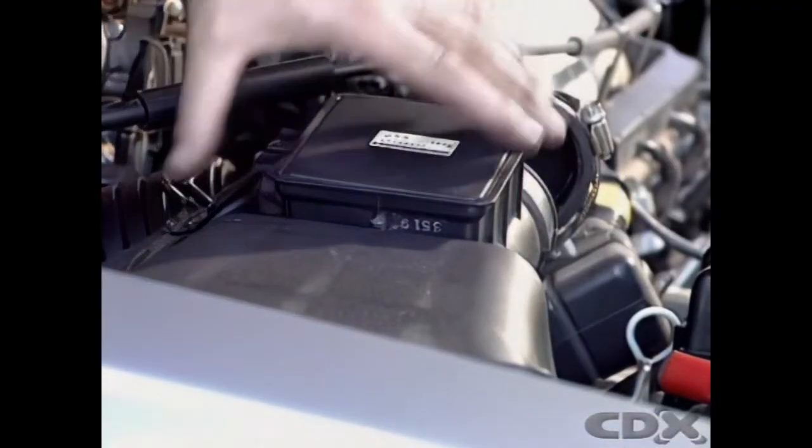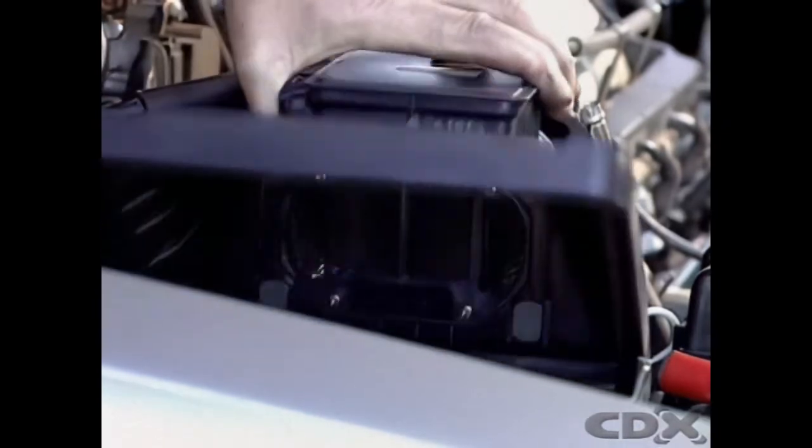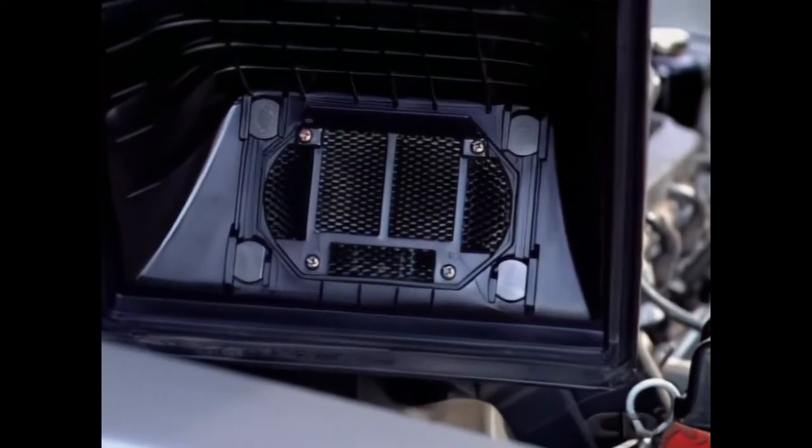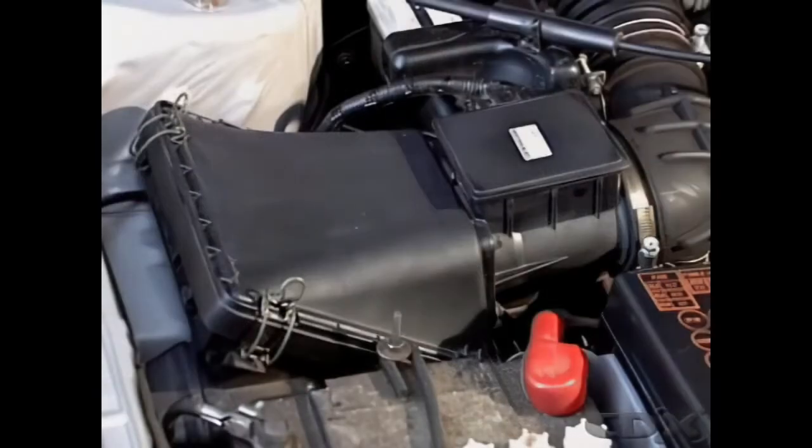Some electronically fuel-injected systems have an airflow sensor after the air cleaner element. It accurately measures all air entering the engine and adjusts the air-fuel mixture accordingly. So it's essential there are no air leaks, or it will upset this mixture.